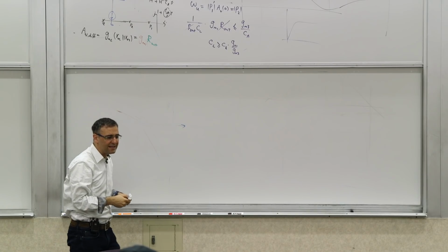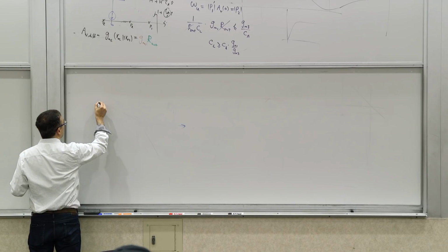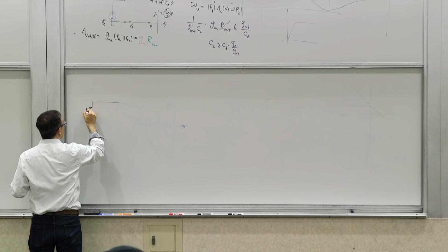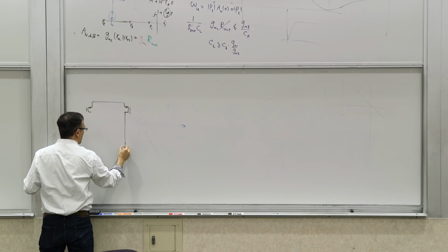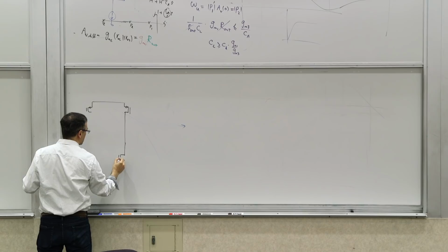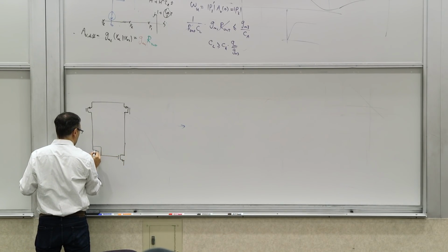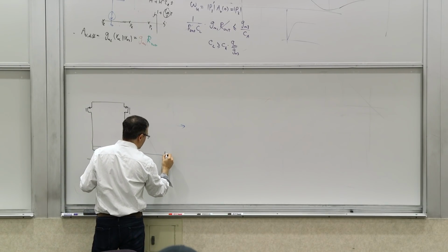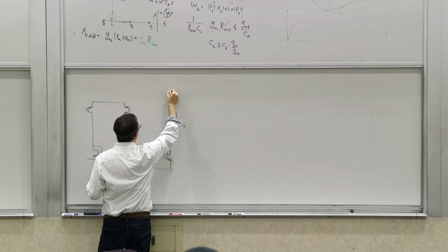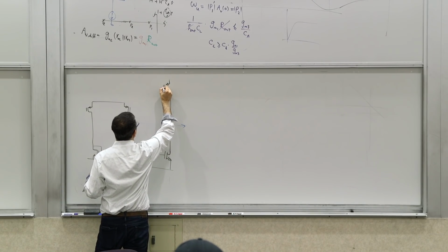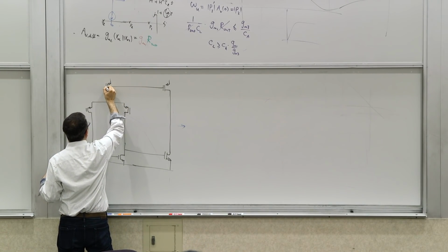So the most basic two-stage op amp that we designed, for example, in MOSFETs, looked like this. You started off with a differential to single-ended converter. In this case, we're starting with a PFET drive stage and an N-type mirror, which went to a second stage, which was a common source with an active load. And then you also have a current source produced here, PFET.